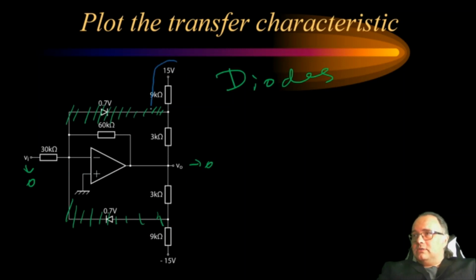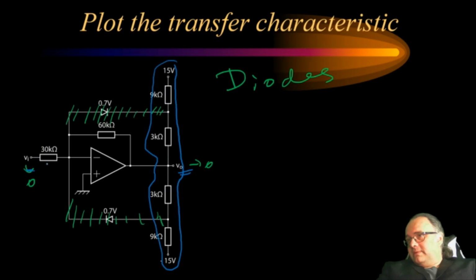It has no connection now to the input, so it cannot influence the transfer between input and output. Now, the relationship between the output and the input is defined by the input resistor and the output resistor. To get it, we have to understand now the concept of virtual ground. Why this node is at 0 volts or very small potential, 0, for all practical purposes 0.